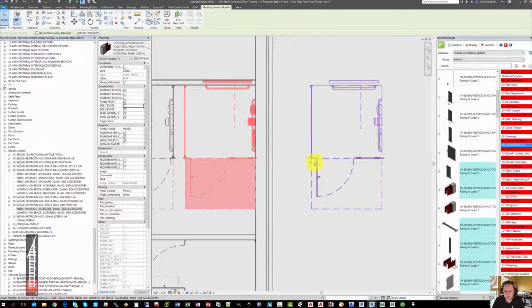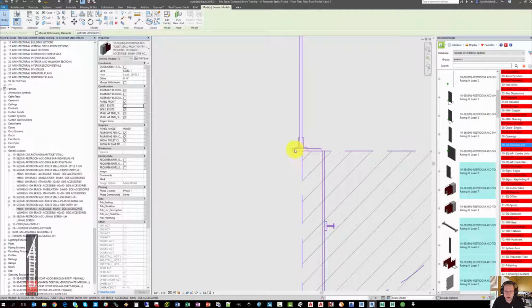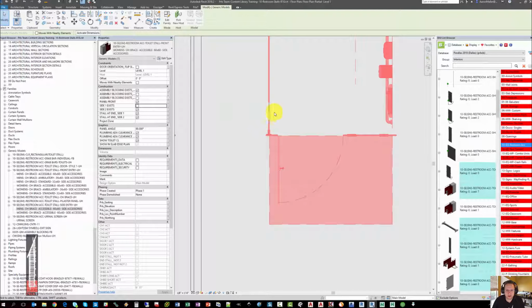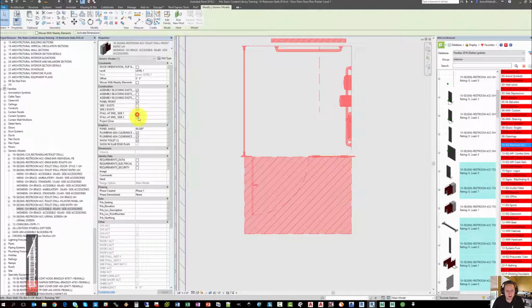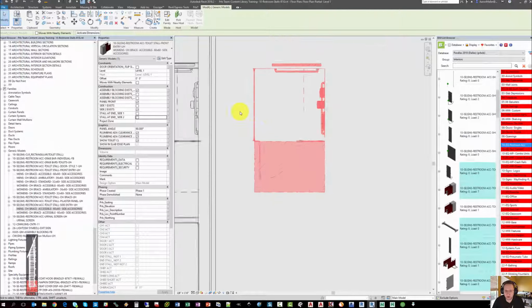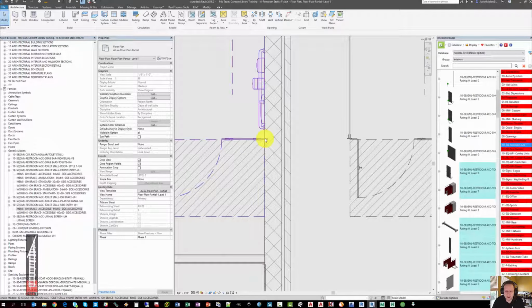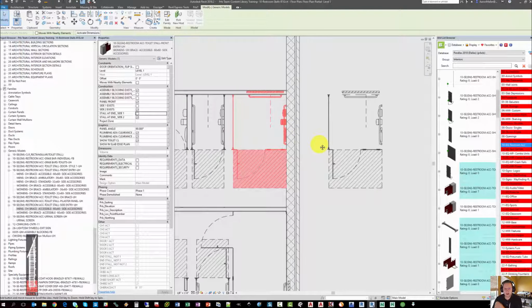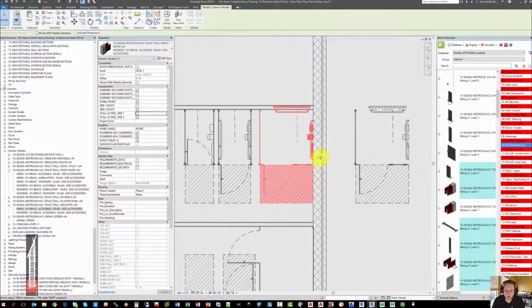You'll also notice that the front wall of the stalls extends past the side walls. That's a condition that relates to, is the stall at the end of the run? That way a pilaster here can actually have some room to anchor into the floor or the ceiling. So if the toilet stall is simply not at the end of the run, you can uncheck those boxes and the ends of the front panel will come in. That will be how we get the wall to come out of the CMU. We'll say that side 1 is not at the end of the run. You'll see that the stall is already starting to look more like what we're after.